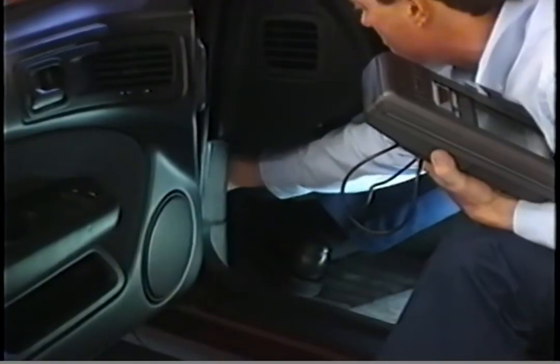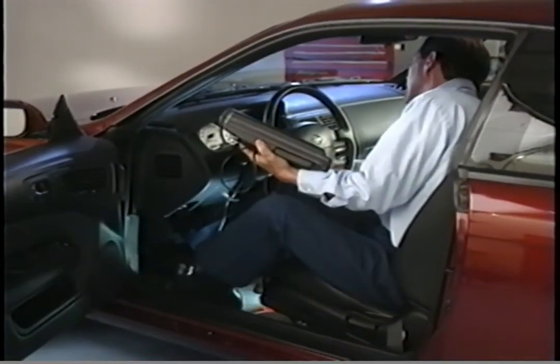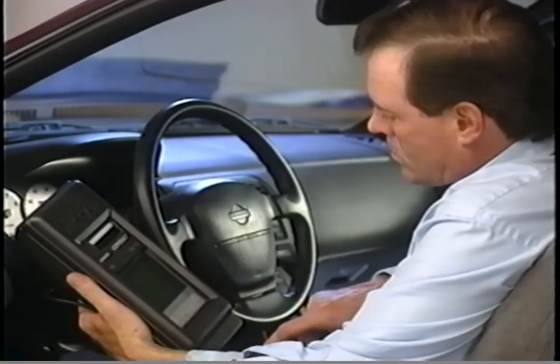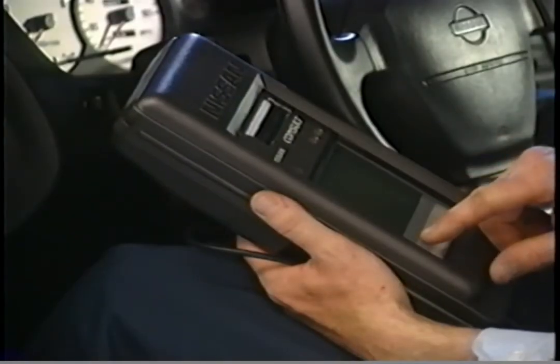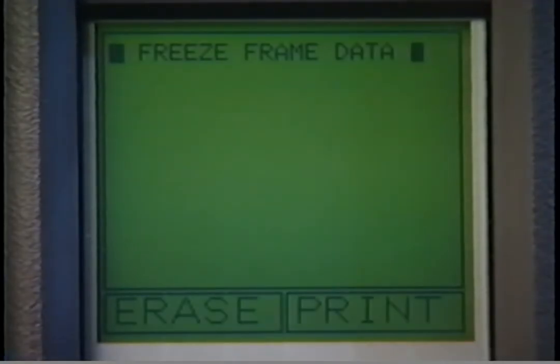Yet even with this technology, you should always refer to the appropriate manuals and bulletins for the details necessary to ensure complete repair. And remember, you still need to follow the normal and usual procedures, which are: verify the malfunction, isolate the systems and components involved, make the necessary repairs, and then check the repair and make sure there are no additional or new codes.